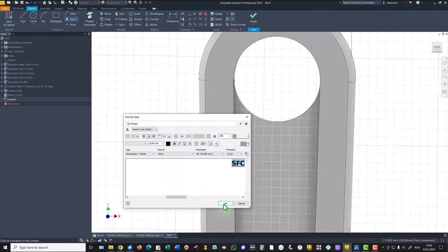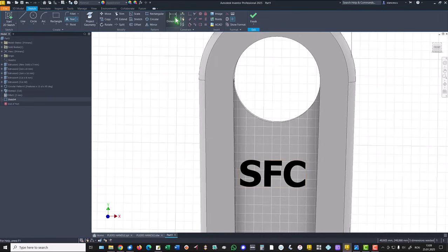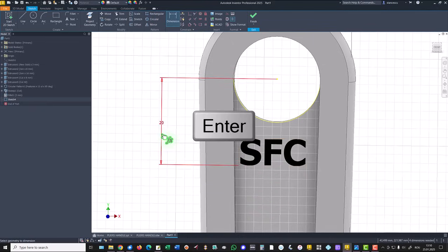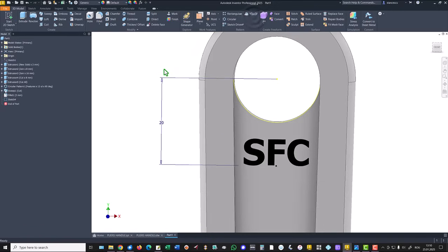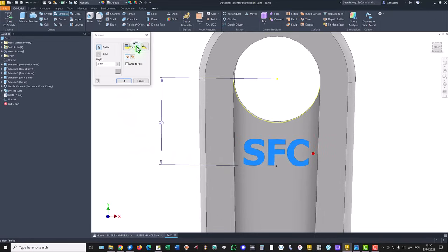Bold. Okay. The distance from this end line to the center, I didn't project it, the center. Let me project it. Now we have a center somewhere here, so that we can apply the dimension of 20. We also place on the same vertical this point with the center of the bottom or upper center. Finish sketch. We use emboss of this profile with cut on 8 millimeters.